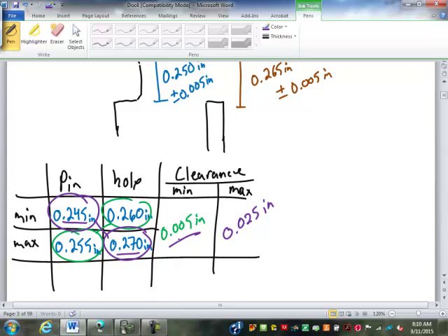Does anybody know what the standard clearance is for threads on a bolt? 1/64. Yeah. It's usually about 0.02, 2/100ths of an inch, a 50th of an inch, but that's between a 64th and a 32nd. So that is basically your thread clearance. That 25 thousandths is pretty close. By the way, if you ever worked with a bolt that has a 32nd of an inch clearance, they won't stay tight. What's that?